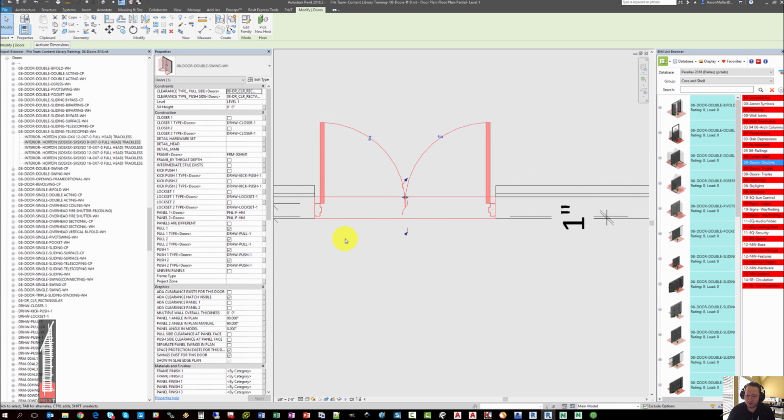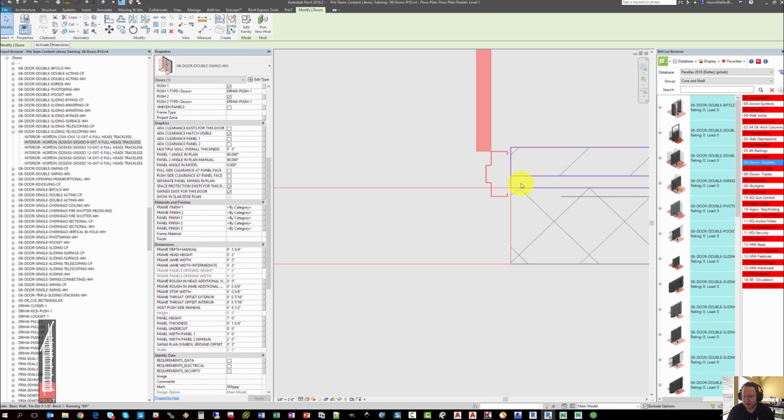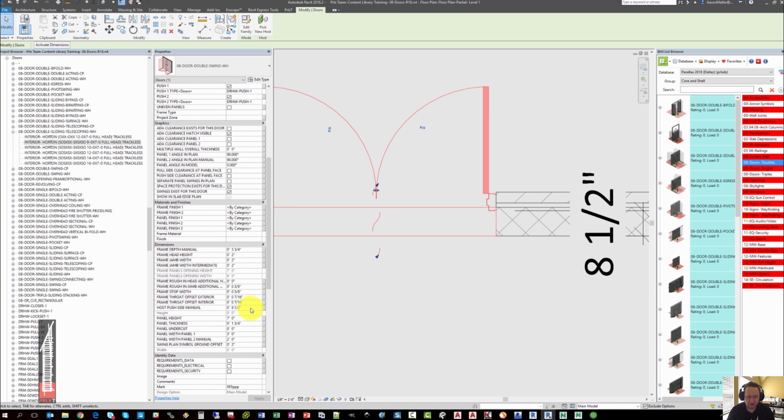This means that you can use this parameter to set your doors properly over the cavity where you'd like them to be seen. For instance, if we make this 8.5 inches, you'll see that we can now get the door frame to cover up the cavity between the CMU and the brick. Realistically, it would probably be more like 7.5 inches, and so we can pull it back.